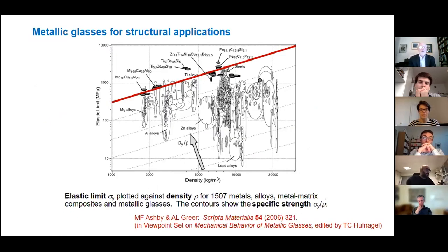The main commercial application for metallic glasses, which is genuinely quite an important one and becoming increasingly important, is as a soft magnetic material for transformer cores and multiple magnetic devices. That's an established area which will, I think, make more progress. Scientific interest in more recent years has been, given that the glasses can be made in bulk, maybe one should be looking at structural applications and their mechanical properties. I won't dwell on that except to say that there are genuine reasons for interest.